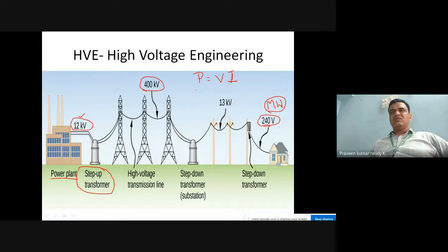So that is a fixed one. Of course it varies depending on the time of day, like maximum demand, peak load and normal load. But for the time being, assume P is fixed; the maximum load we can offer to the power system is in megawatts. And if V is smaller, like if I transmit in the 12 kV range, the I will be very high, since P is constant. Megawatts is a fixed load for the entire city. Now the only variables here are V and I.